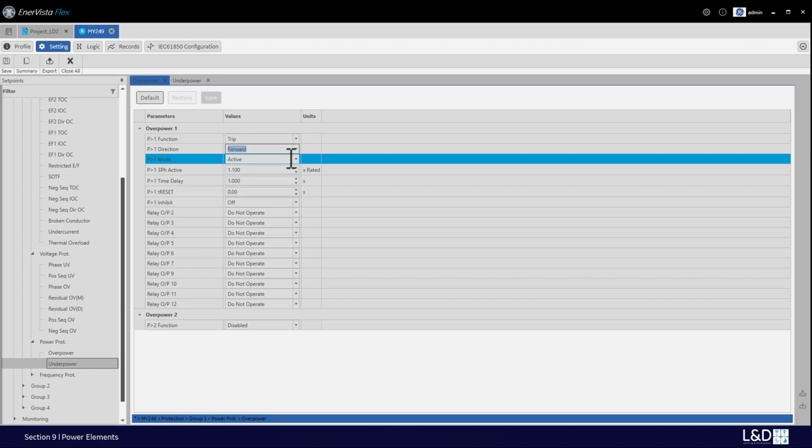This reverse power flow usually happens due to loss of prime mover. Depending on the type of the prime mover, the reverse overpower can be set less than 50% of the motoring power. The typical levels of motoring power for various types of generating plant can be found in the instruction manual.